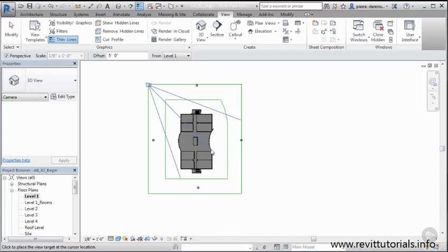Anything within these lines is going to be visible in my model. So the top angle and the bottom angled lines, not the middle, but the top: anything that's excluded outside of those 2 lines won't be seen in our model. So you want to make sure that you include everything within your model here. Also, how far you drag this out is going to determine what's visible within your model in the distance, right? We talked a little bit about being able to see things through the glazing or being able to see background elements. Well, this is going to determine that as well.